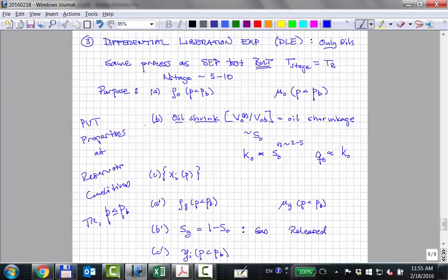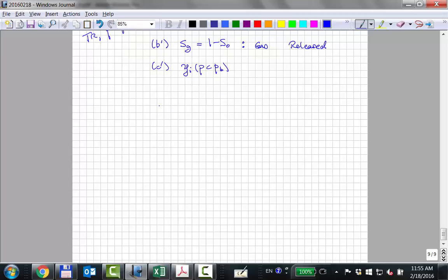So the experiment's very simple. Okay, it's a very simple experiment. You can actually use a blind PVT cell because you actually get the gas volume, because you take it away, you know how much gas volume it is. I mean, in other words, if we start at the bubble point here, say at the bubble point, so it's only oil, and then we make the cell larger.